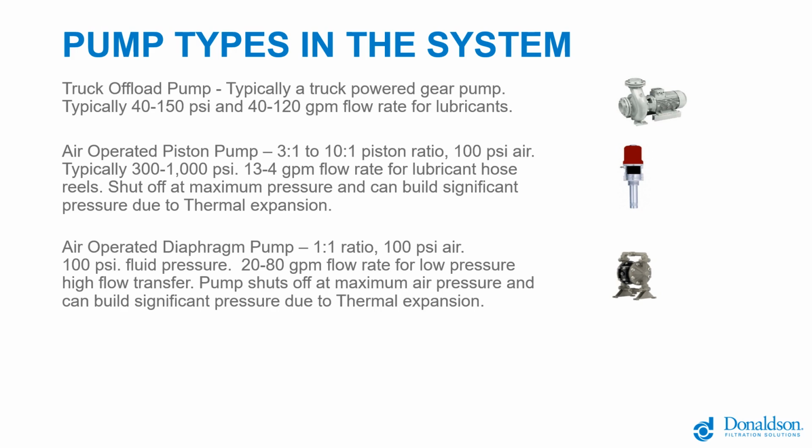But these pumps also shut off at maximum air pressure, and they can create a situation that I'd like to mention here. This is a very serious aspect of these styles of pumps that shut off at maximum pressure. I want to talk about something called thermal expansion.